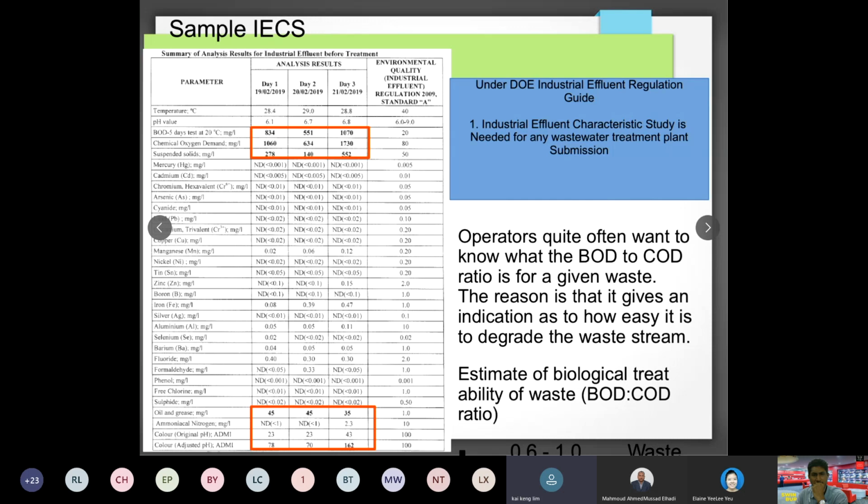For the environmental engineers who join us, we ask them to do some paperwork and to test some of the water chemistry, because our company has a small water lab to help customers measure COD, BOD. I think nowadays the government is enforcing the competent person requirement, a certification for a person who understands how wastewater treatment works. This wastewater person will know how to test certain parameters like COD, pH and suspended solids, and how they are actually tested.